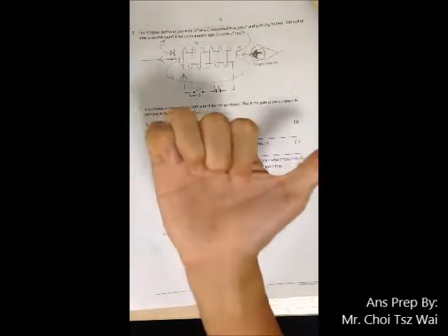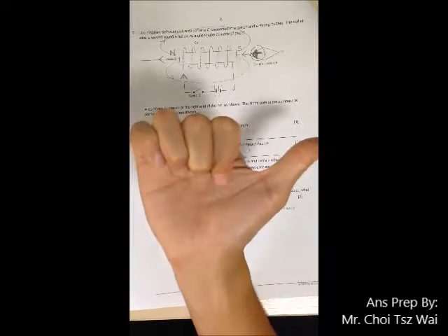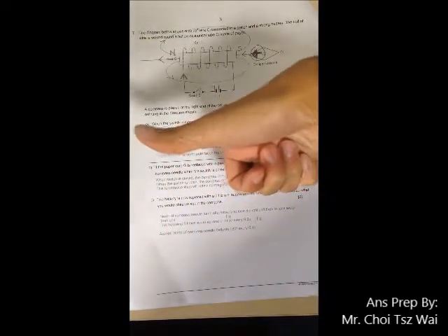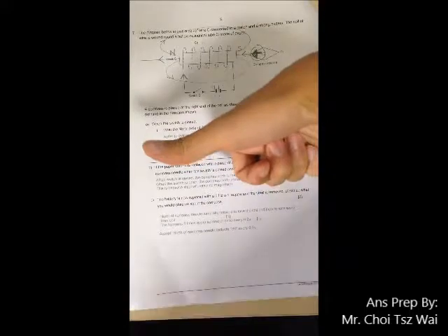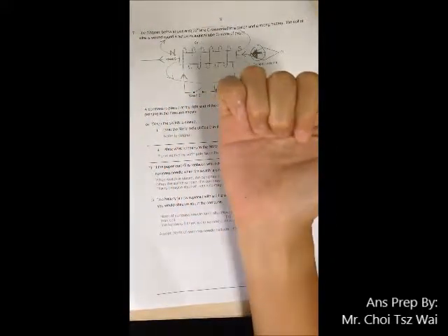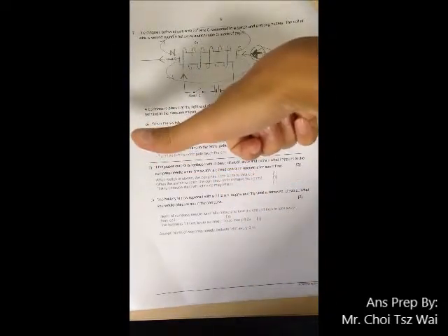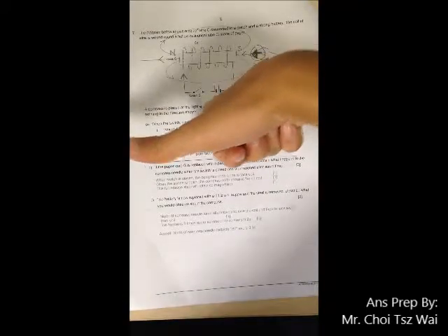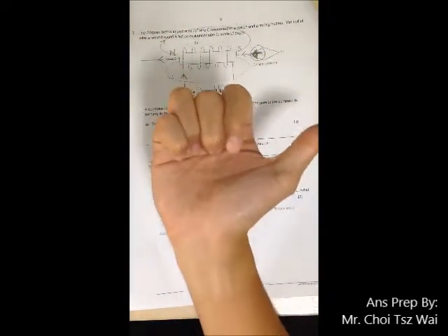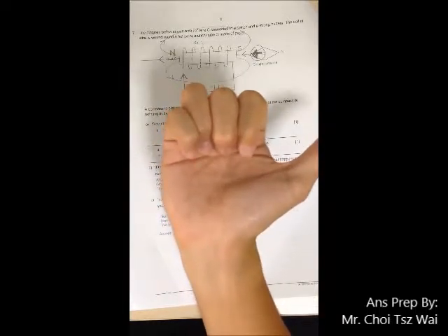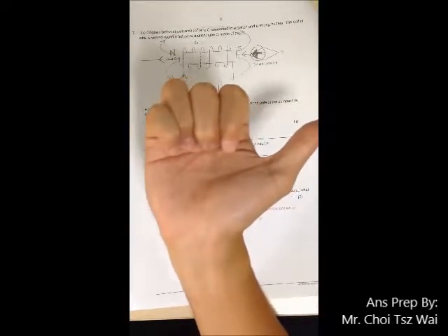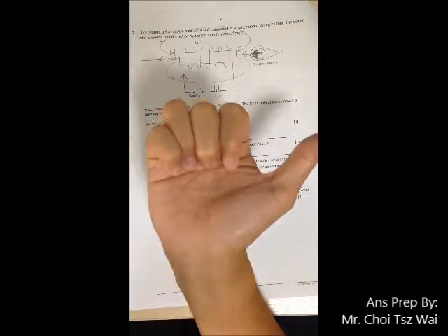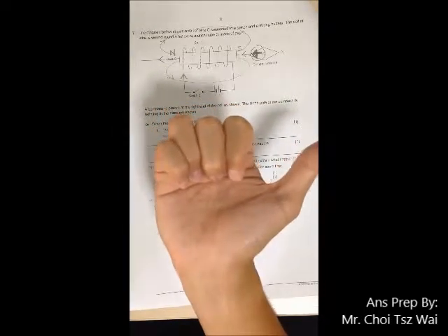initially was this way, pointing to the right. When the switch is on, it will turn this way because it will follow the magnetic field line. So state that when the switch is closed, the compass will quickly turn to face the coil. And when the switch is open, normally when you have the paper core, the needle is going to return because it's no longer being influenced by the magnetic field from the coil, because you have switched off the circuit, right?